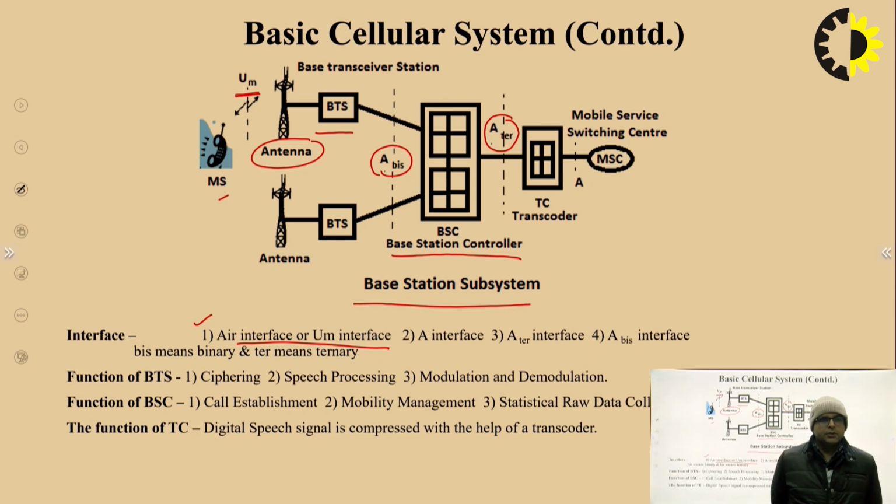The base station controller performs many functions like call establishment, mobility management, and statistical raw data collection. This BSC, base station controller, plays an important role in establishing the call. Apart from call establishment, mobility management is very important in a wireless communication system, because in a wireless communication system the subscriber is not static, but mobile.